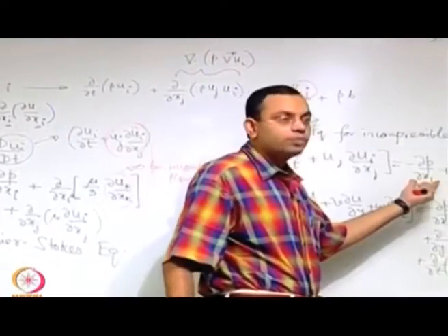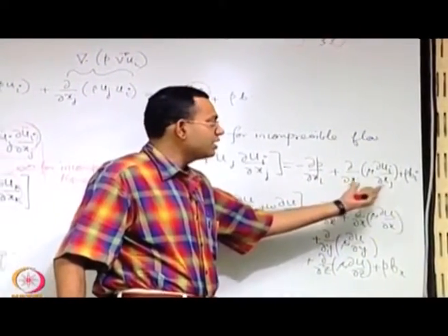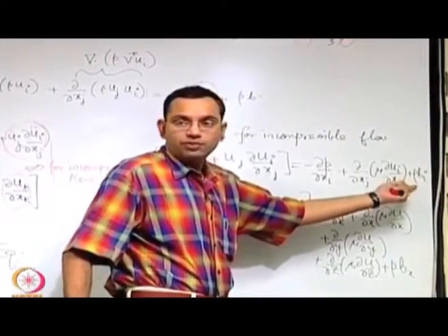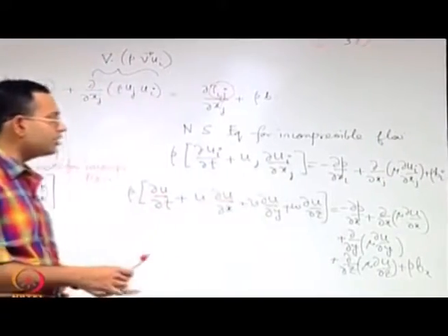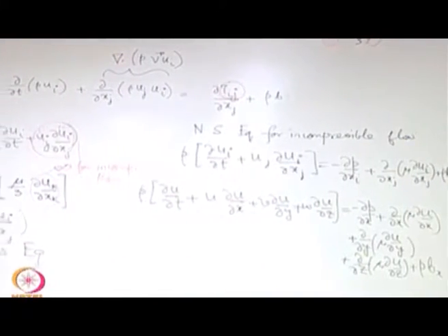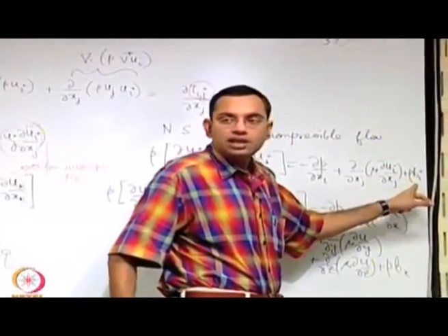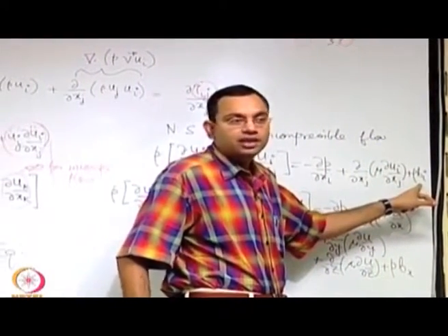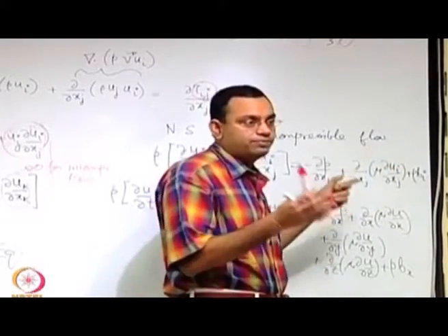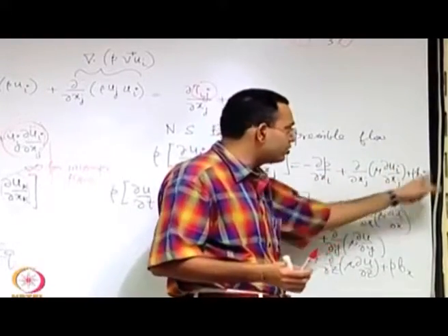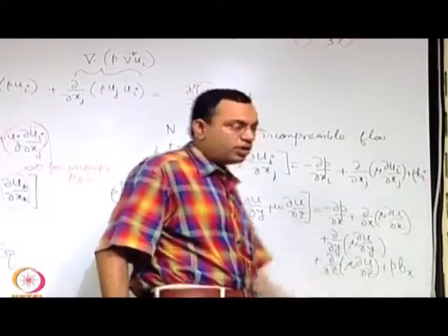This is a force due to pressure gradient, this is a force because of viscous effects, and this is a body force. The body force may be anything, like it may be because of gravity or whatever, but it is important to recognize that it is a very general force that we have kept here. So there may be effects of electrical field, magnetic field, or many other forces may influence the fluid flow, and all those extra effects will be appearing in this form of the body force.